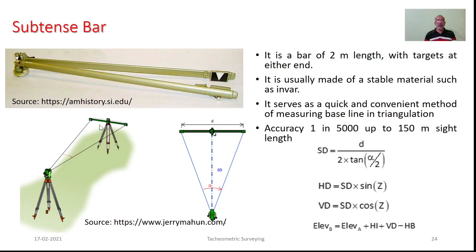Both the equipment will be centered exactly by making use of normal leveling and centering processes. Here, by making use of that particular small telescope, we can refer to the plumb bob hung at the theodolite end. As such, this particular face would be made 90 degrees.